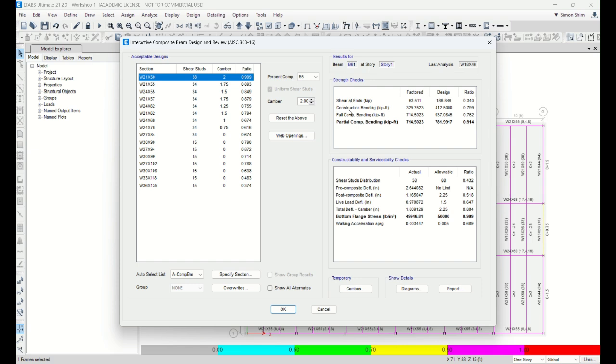So as I mentioned before, composite beam design actually goes in two phases. One is during the construction phase, when the concrete is not cured. It's wet concrete. The steel beam should take care of all the wet concrete weight, so you can calculate this with 1.2D plus 1.6 live load, manually, or maybe double check by hand.